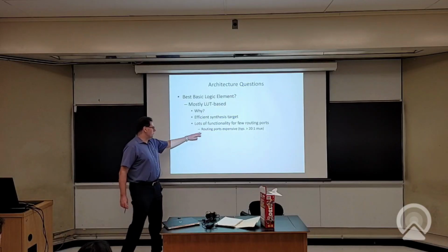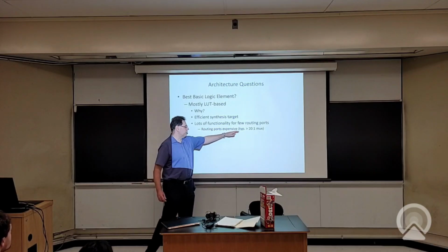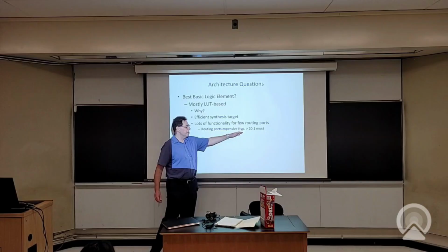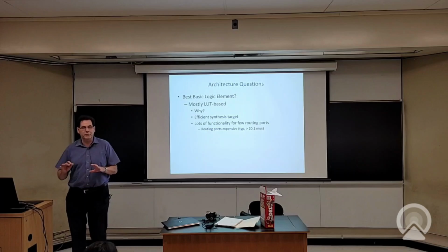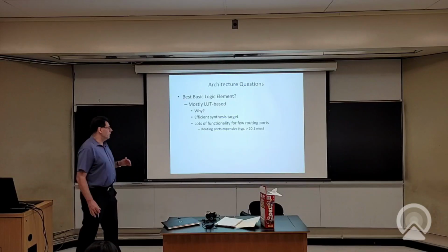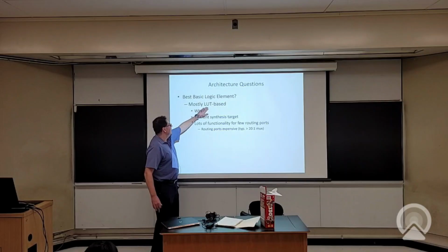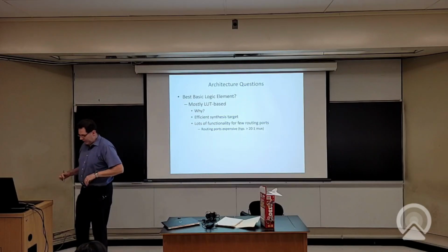Because these routing ports that connect you into the general FPGA routing, they're expensive. You get to choose how expensive, like how big do I make those muxes, but usually to make things route pretty well, the amount of muxing is reasonably large, right? So like a 20-to-1 mux or more would be typical to connect a LUT input into the local routing or into the general outside-the-cluster routing. So that's pretty expensive.